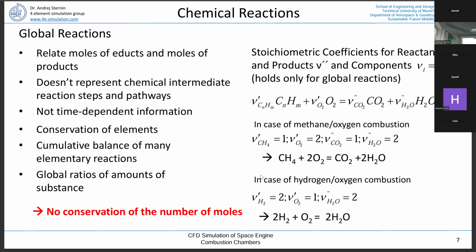So this is not in the system, and sometimes it's important, in particular if we do rocket engines, because in the center of the combustion chamber we normally have 3,500 Kelvin, independent of whether it's hydrogen, oxygen, or methane or any type of hydrocarbon, it's 3,400, 3,500 Kelvin, depending on the pressure and mixture ratio.